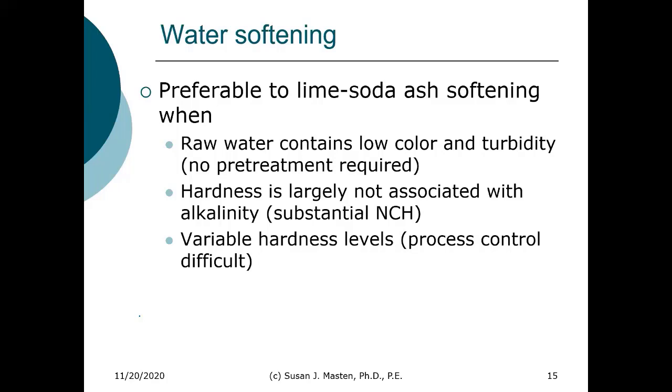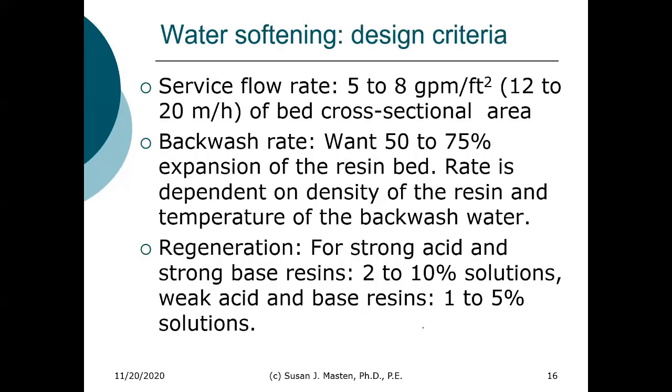Typically, if you have a high amount of non-carbonate hardness, then ion exchange is preferred over lime soda ash softening, or if you have very variable hardness levels, so that process control is difficult with lime soda ash softening, ion exchange is better there. I'm going to end there.